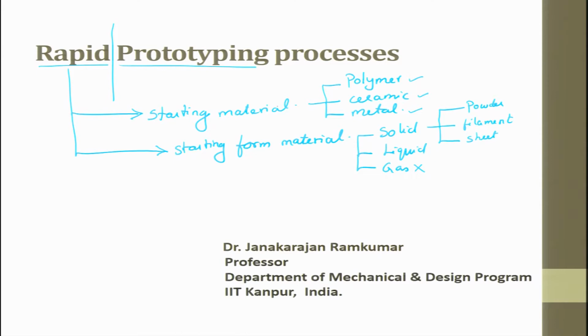Now, when you choose the material, correspondingly we have to choose how to join these materials together such that you can form a prototype. Here, the polymer which exists in liquid form is chosen, and when we want to convert a liquid into a solid, the process which happens is called photopolymerization. A liquid to solid conversion is polymerization.